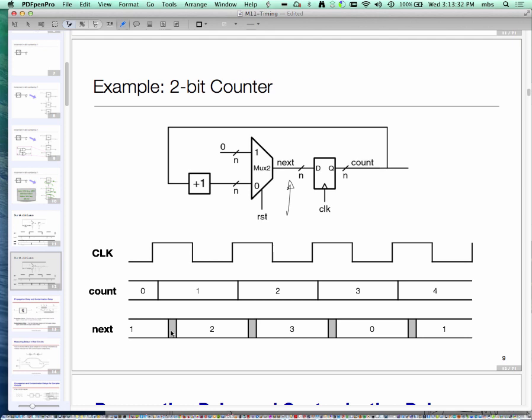Yeah. Is that caused by the adder or the multiplexer? Adder, right? The adder would be the primary culprit out here. Yeah. But it could also happen because of the multiplexer, because maybe different bits of the multiplexer don't have exactly the same delay. Okay, so it can happen through anything, but the adder clearly would be a big culprit.